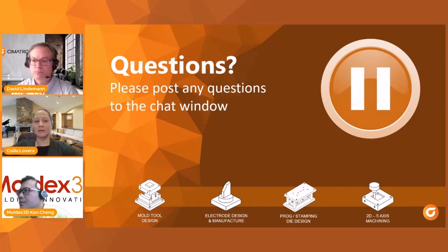Thank you, Casey. And there is one commonly asked question. What is the typical time that it takes to get the warpage model in Moldex3D? So in order to run cooling, flow, pack, cool, warpage, usually one model takes a few hours, and you could run a couple iterations in one day. So it takes a few hours to get a warpage from Moldex3D, and then with just a few clicks, you could export the STL model to Cimatron. So a couple hours.